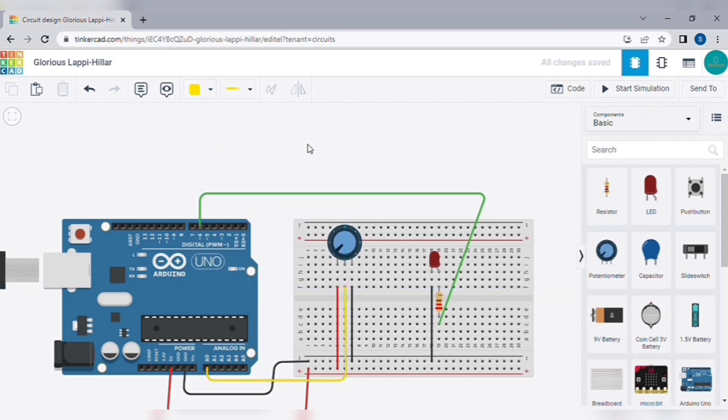So the question is, why an analog pin? We know a digital pin can only provide either 0 volt or 5 volt, meaning off or on. So if you want the intensity of light at half of the maximum value, 2.5 volts is required for that according to the circuit, but we can't achieve it by using the digital pins. Analog pins are capable of providing values in between 0 and 5, like 2.3, 2 volts. So that can be provided by the analog pins.